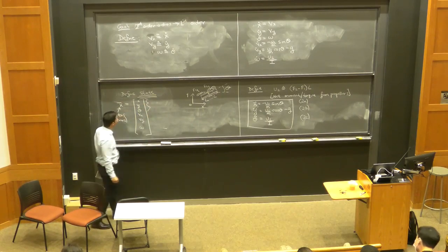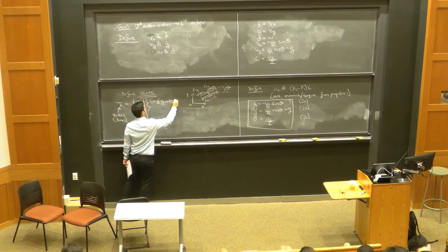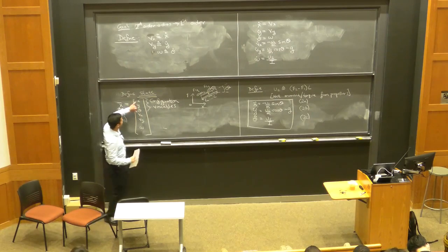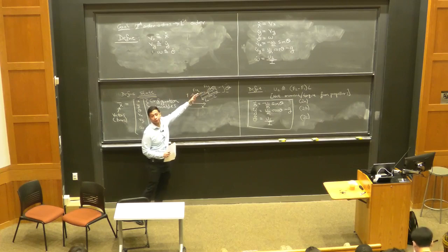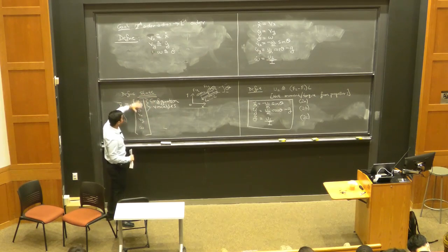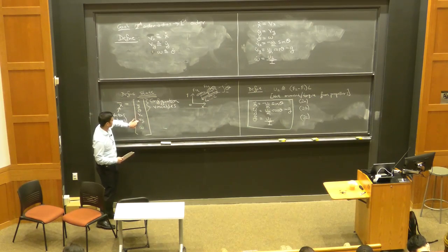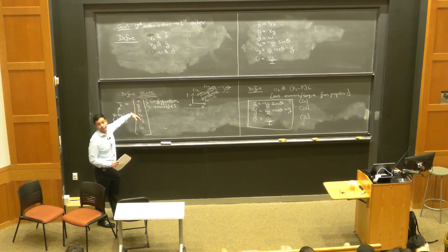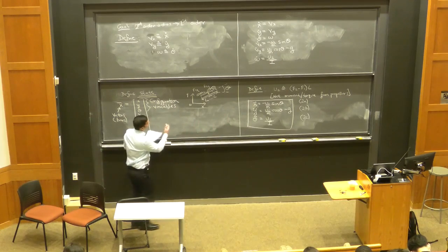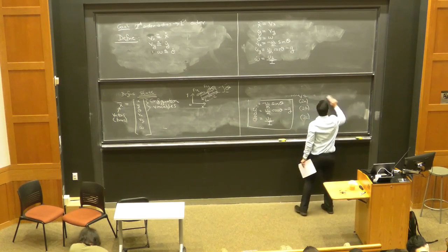These first three variables, x, y, theta, we're going to call configuration variables, because if I specify what these numbers are, that specifies the configuration of the system. In general, the number of configuration variables corresponds to the number of degrees of freedom, so each of these configuration variables gives us one independent way that the system can move. And these quantities, Vx, Vy, omega, in this case just happen to be the time derivatives. But they're basically everything that appears without the dot on the left-hand side. So what we can then do is rewrite these equations in a standard form that we use, like I said, throughout the course.